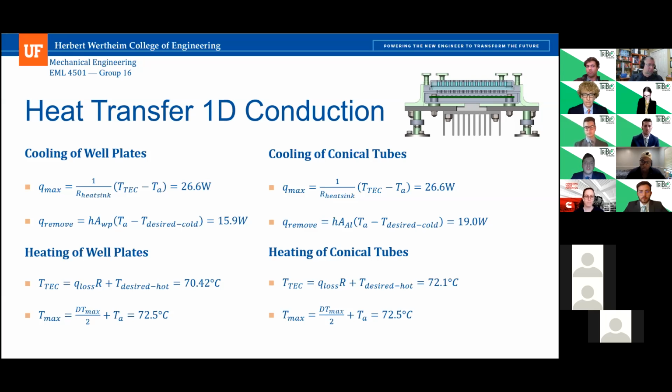The box should only reach maybe 30 degrees Celsius. Well, I'm not so concerned about the outside temperature of the box. It sounds like that'll be well within the limits. But if internally the box is getting warm, that's going to further reduce the efficiency of your heating or of your cooling. That is true.